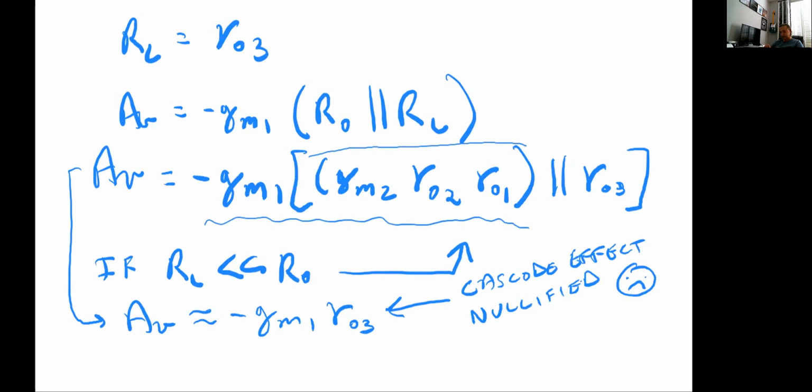And we're looking at the small signal and biasing, but we're assuming that the amplifier has an infinite bandwidth, but that's not the case. There are other effects and other capacitive components that we can put into the small signal models to do all the analysis that we're doing. We can do it as a Laplace type analysis and see that all these quantities are frequency dependent.